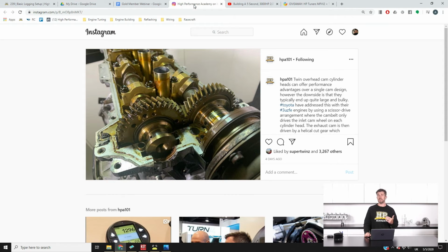This is something that is unique to some of the Toyota engines. Well, Toyota actually kind of adopted this and ran with it with quite a few of their engines, so maybe saying unique isn't quite right. But this is the cylinder head here, and obviously it's a twin cam cylinder head, but while it's out of shot here, this is the cam drive pulley. So this is what the cam belt actually drives. We've only got one cam sprocket for 2 cams. So the advantage with this is it allows quite a narrow cylinder head design, keeps the packaging nice and neat. And there are some implications there around valve angle as well, but probably a different discussion for another day.